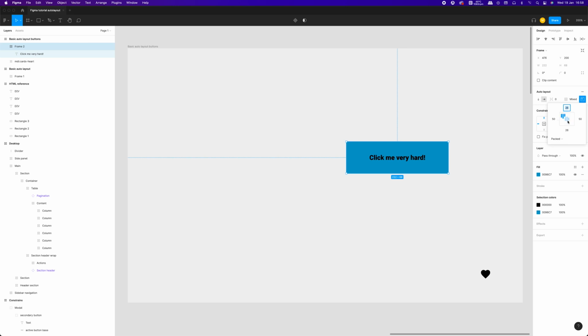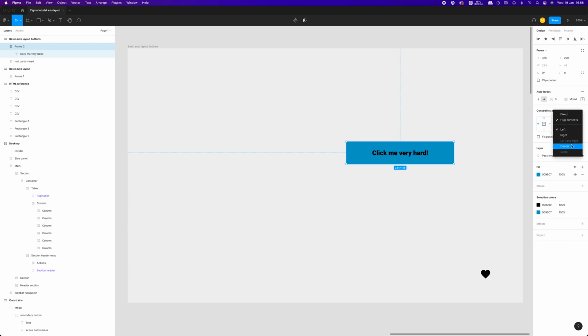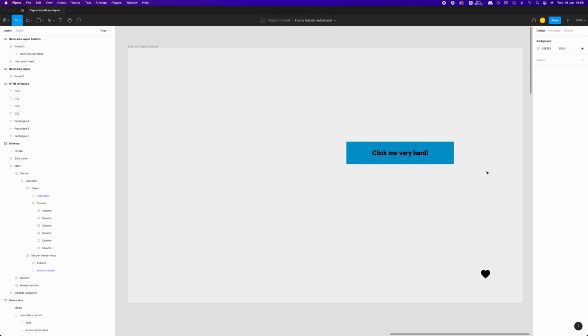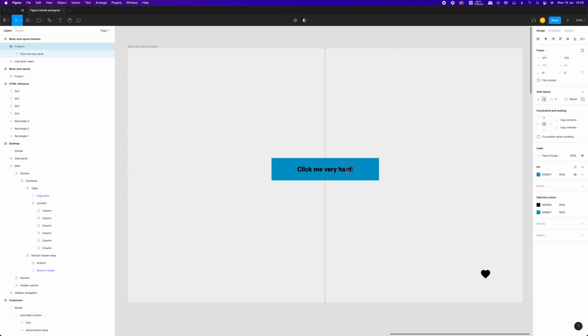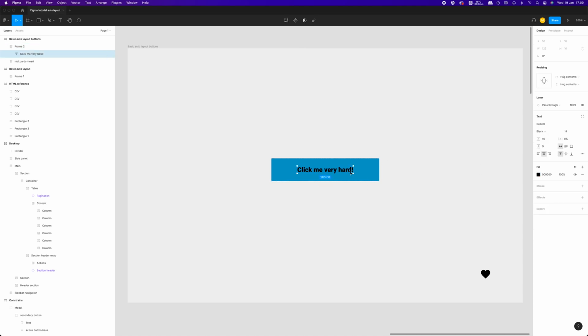So let's click alignment and padding in the properties panel, set alignment to center, top paddings to 16 points and side ones to 56. Now let's go to the constraints panel and set width constraint to hug contents and centered, and height constraint also to hug contents and top. That way our button will maintain the paddings we set and adjust to the text we put inside it.